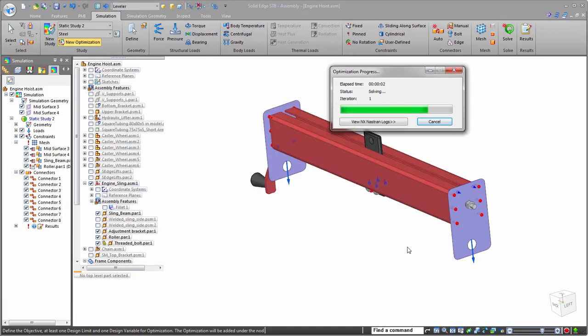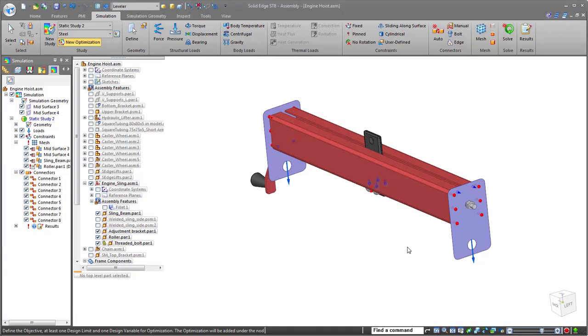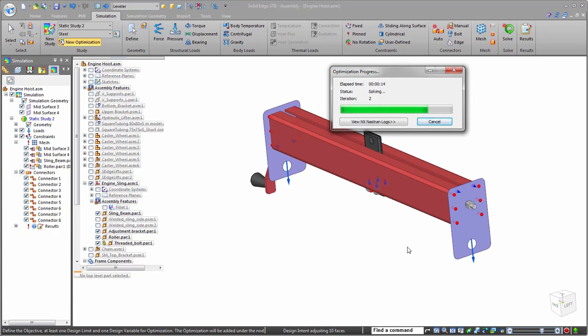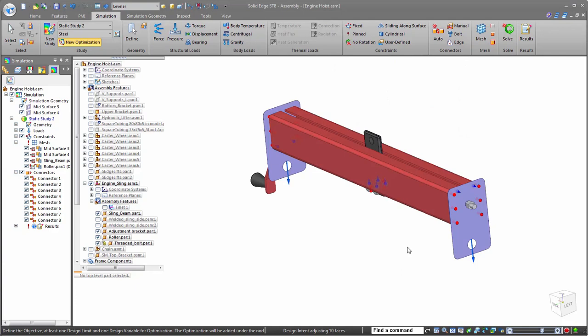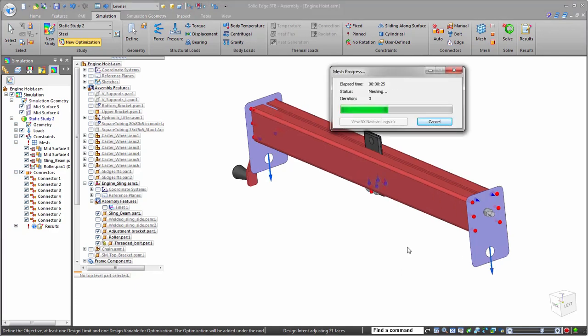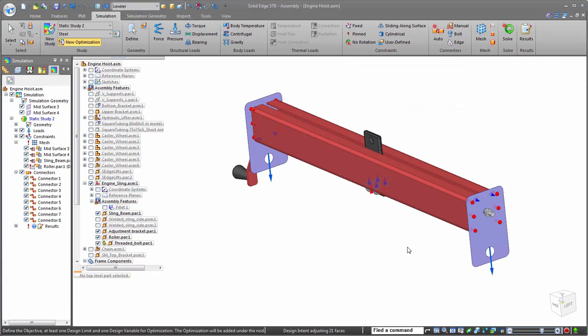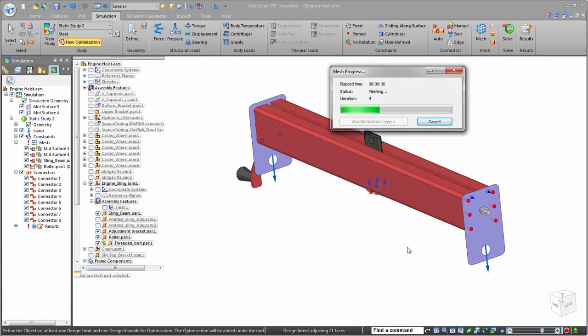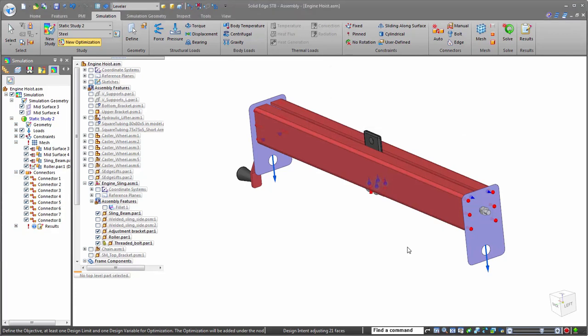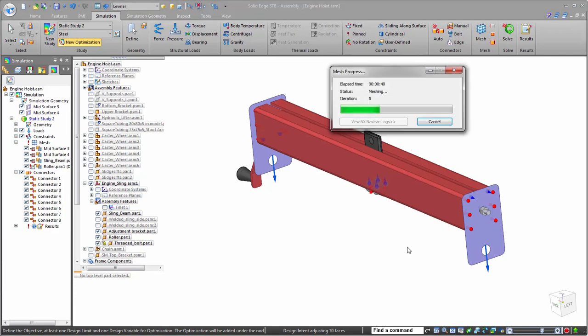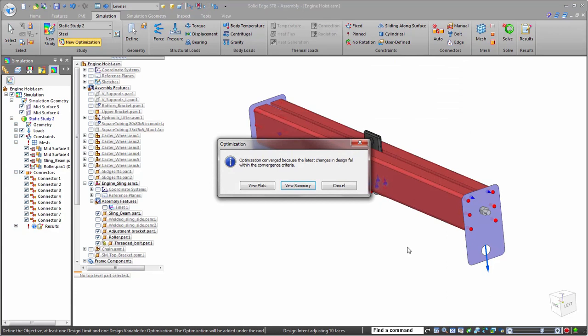Now, while you're optimizing, you're going to go through 6 iterations, and that's going to take about a minute to run through all of those. Now, if you look at the script that was delivered alongside, there's a lot of great information there as far as what's taking place as it iterates, as well as making sure you point out that this is FEMAP and NASTRAN that is powering the solving, and the amount of time saved without any kind of designer input, and being able to find the most optimized condition for your solve. So it's just going to go ahead and run through this actually pretty quickly.